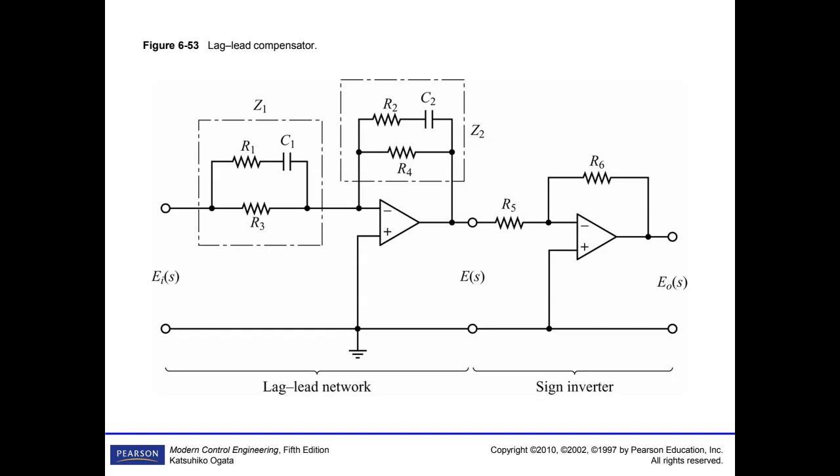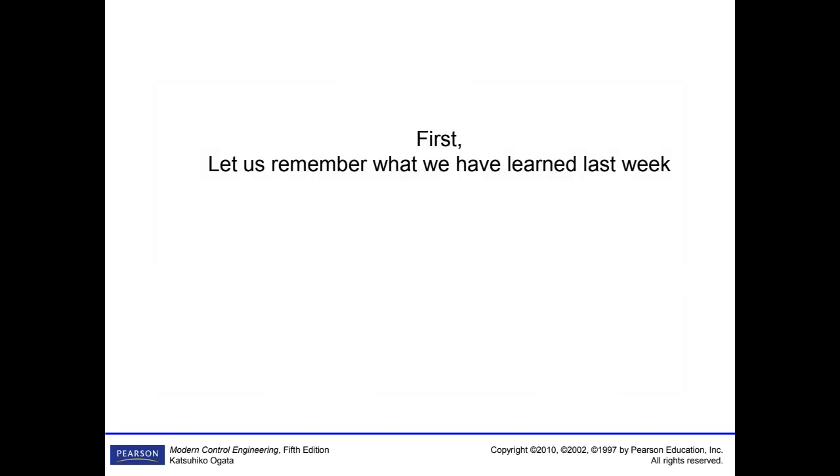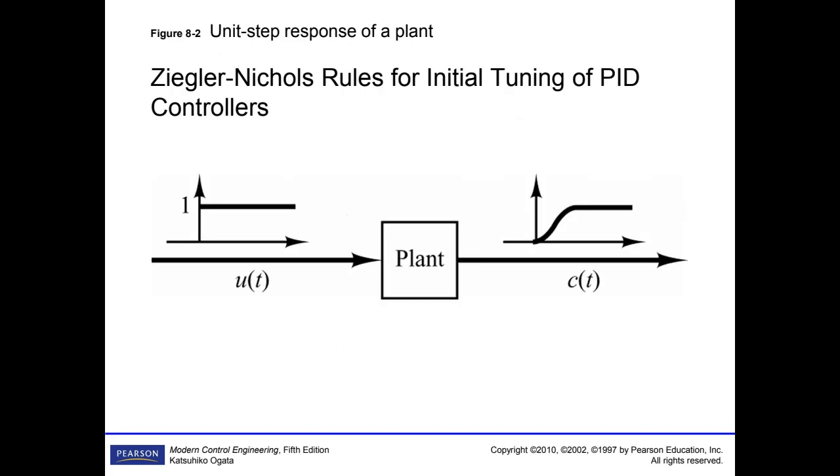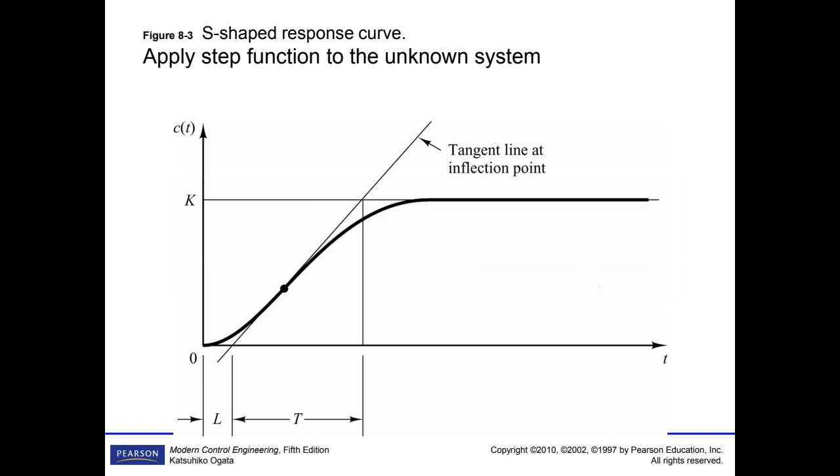PID, we have three parameters. It's difficult to obtain the starting point from zero to infinite. From zero, I mean point 0.0001 for example. So infinite numbers. So we are going to use either the first Ziegler-Nichols method, with L and T, and look at the table here, obtain Kp, Ti, and Td, or if there is an oscillation, we use the second Ziegler-Nichols method.